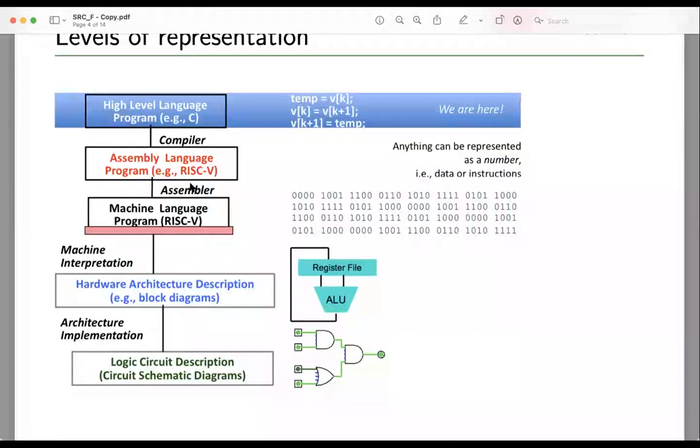And this machine level code depends on the architecture of your processor. Here I have written RISC-V. You have an open power core also now, which is Microwatt. So the idea is, from a high level language, we now understand the context of the instruction set architecture, which you have already seen in the previous lecture. The instruction set architecture helps us convert the basic high level program into equivalent instructions which are supported by that specific microprocessor or that particular computing element. I just give it a name, computing element.